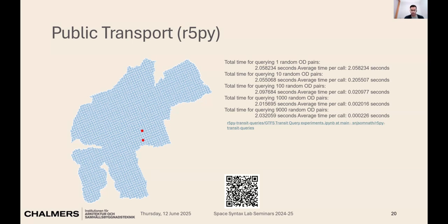So what the travel time matrix does is it consumes a GTFS specification for the public transport system, which includes trams and buses in the case of Gothenburg in Sweden. And it has a timetable for all the different lines of public transport. And it takes into account a departure window when people actually move from their origins. So in this model, it's a single departure window that's taken into account at the peak travel hours in the daytime. So I think we're looking at somewhere between 7:30 and 9 for the travel window, but you could, in theory, have multiple travel windows to dynamically change throughout the day.